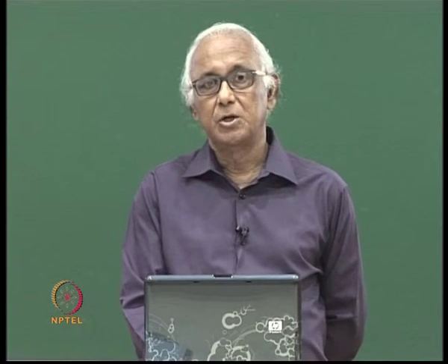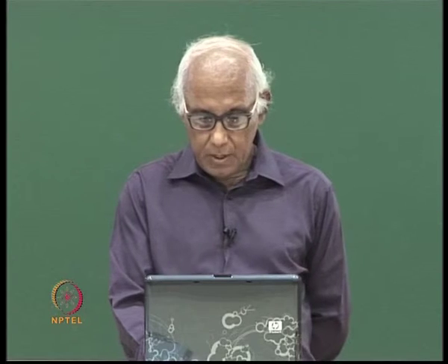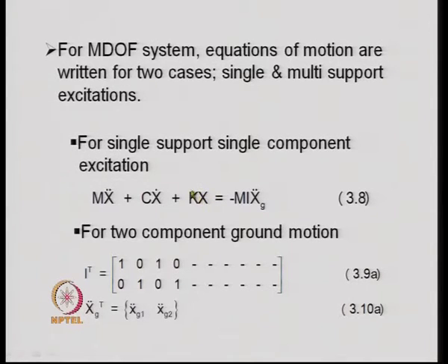By definition, a dynamic degree of freedom should have a mass attached to it. So, this K in fact is a condensed stiffness matrix of the structure corresponding to the dynamic degrees of freedom.